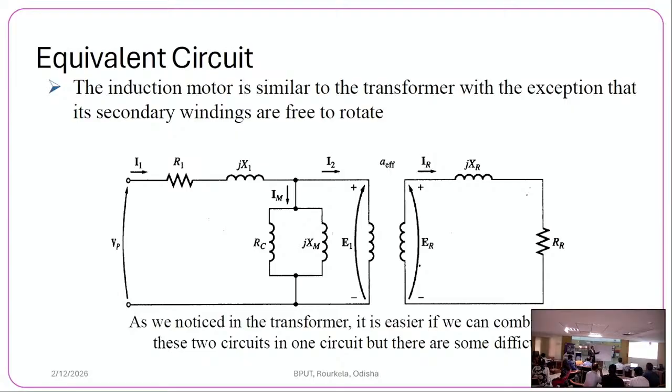So there are two inductances. Let us consider the stator side. One inductance is here, a reactance. What is it called? It is the stator reactance, the stator winding reactance. So when we are transferring something from the rotor side to the stator side, some anomaly occurs. And that anomaly is the fictitious reactance, because that S term will come in and make it complicated, then